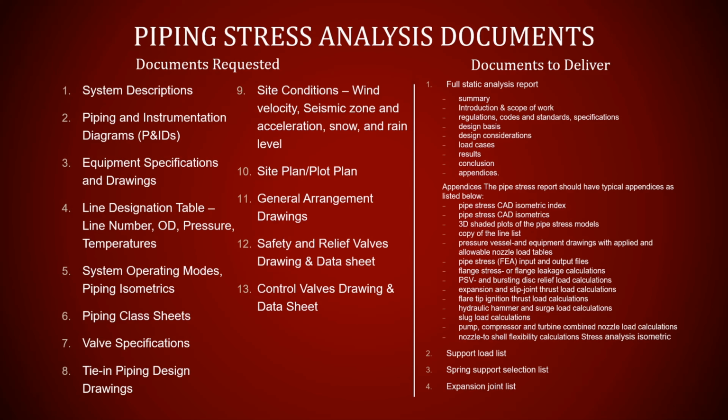What will be our deliverable? First of all, a full static analysis report. The full static analysis report should consist of a summary of the whole report, introduction and the scope of work, the regulation codes that we are using, the design basis that we considered our calculation on, the design consideration, the load cases that have been used, the results, conclusion of the results, and appendices.